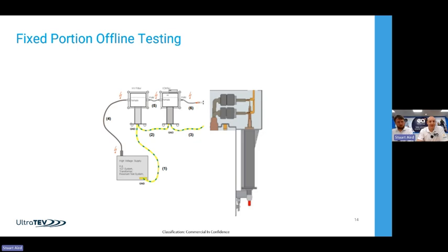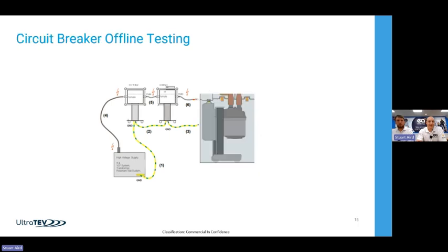So we did two tests. We did one where we just went up through the spouts onto the circuit side. So we basically got the circuit spouts, the CT chamber, the CTs, and the CT bushings. And the second test that we did was the circuit breaker on its own. So we took the circuit breaker out of the switchboard and tested that to see if there's any partial discharge on each. The advantage of doing it offline, you can narrow it down now per phase as well.